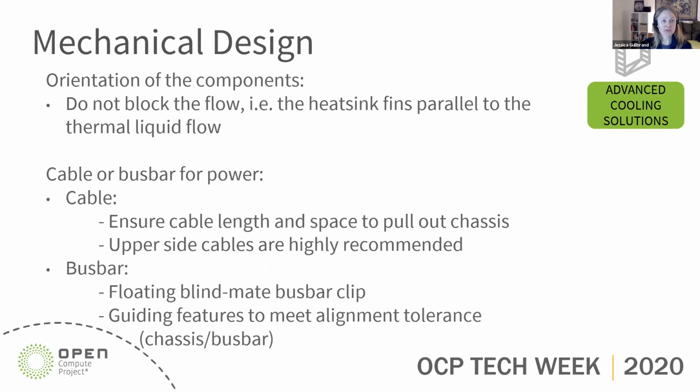There's also orientation of the components. So we talked about, for the thermal design considerations, that we want to make sure that we're not blocking the flow, and how we can enhance the flow going through the IT equipment for enhanced cooling capabilities. So we want to make sure that during installation, for example, heatsink fins are parallel to the thermal liquid flow, so if you're using forced convection together with natural convection, that they're working together.